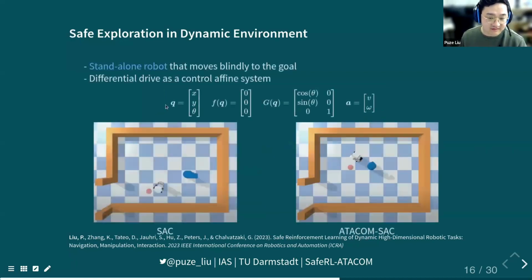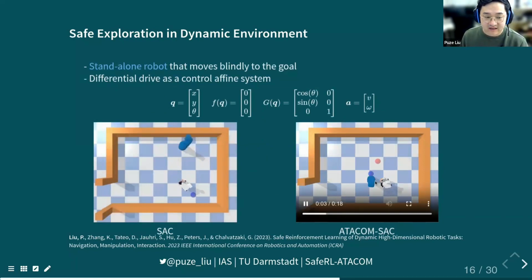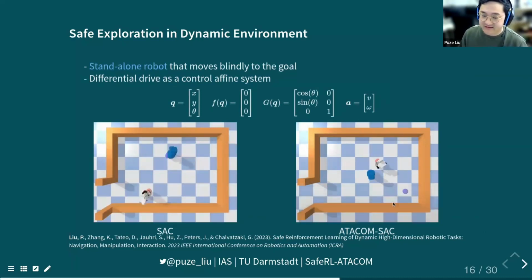For example, in this kind of scenario, we tested observing the state of the blue robot, computing the state based on the robot, or completely assuming the state to be 0. All of them work decently well, but definitely if you know the full state of the robot, it works the best. For the human-robot scenarios, we don't have access to the human's joint velocity, so in that case we assume the velocity goes to 0. But if you don't observe the states, that will be problematic.